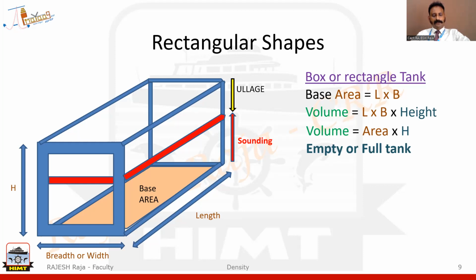In all your tanker calculations, you'll be dealing with ullage, not the sounding. All those candidates who are not tanker, I'm sure you're already familiar with the sounding, but you may not be familiar with the ullage in case you have not calculated. Let me briefly tell you that in tankers, for any measurement with a tape or any fixed instrument, we always take the ullage, then convert into the sounding and then do the volume calculation. So for you, ullage is very important to understand, and how it is given. Ullage is that empty space, the vertical height of the empty space.